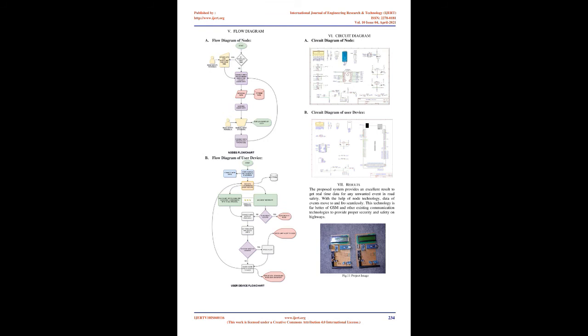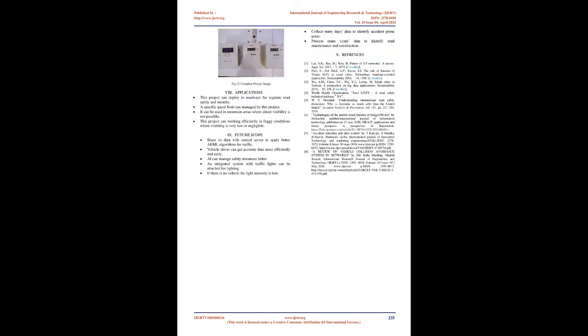The current consumption for the nRF24L01 Plus is extremely low: under the transmitter mode, when the transmitting power is 0 dBm, the current consumption is just 11.3 mA, under the receiving mode, it is 13.5 mA, and under the power down and idle mode, the consumption is even lower. As for application, it's widely utilized in many devices like wireless mouse and keyboard, game handle remote set, industry sensor, toys, etc.